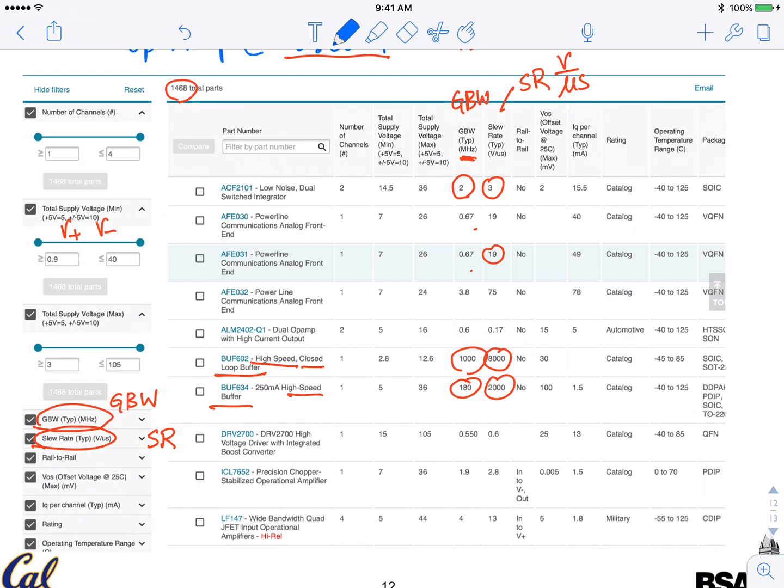And then you find your circuit and apply, remember the nulling to make sure you operate passing the origin, and you take care of your bias current, or you choose a MOS input stage which doesn't have bias current.